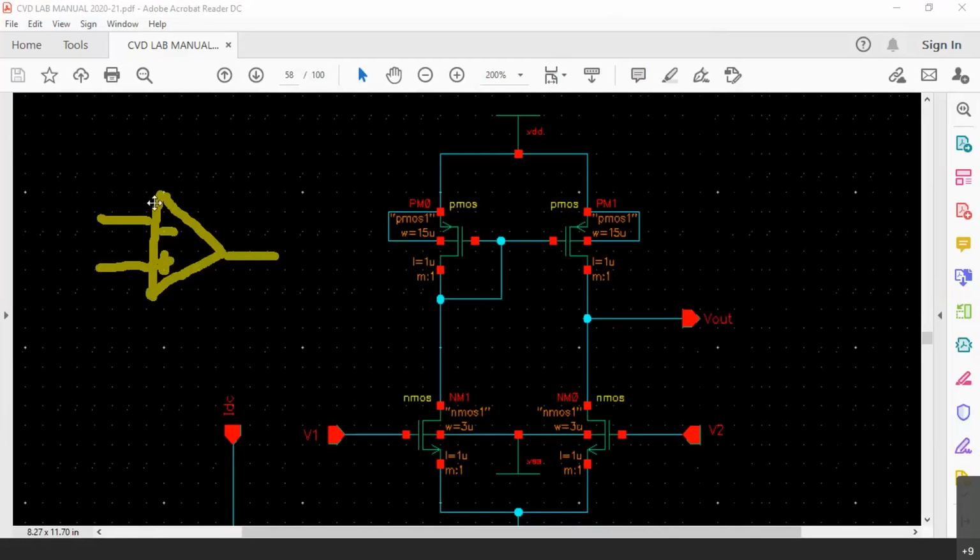So the differential amplifier is going to amplify the difference between the two inputs V1 and V2. And typically we can say that the gain of the differential amplifier is A, the open loop gain. In general, the open loop gain will be very high. We connect one feedback resistor as a negative feedback to reduce the gain. In case of an op amp, you know that. But in case of a differential amplifier, we need not assume that the gain is infinity, because we are dealing with a single stage amplifier now.